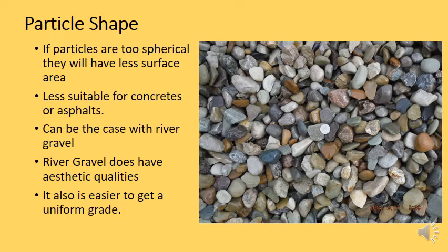But it's a very popular aggregate to use for concrete here in Kurdistan. And the weakness of that, and the reason why sometimes concrete fails and breaks in Kurdistan, is it does have a lower surface area. And so obviously it can break out of the cement and the concrete cracks and fails easier than if the concrete was made with a crushed rock aggregate.